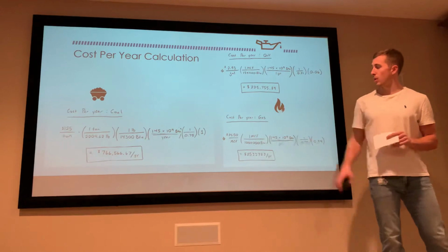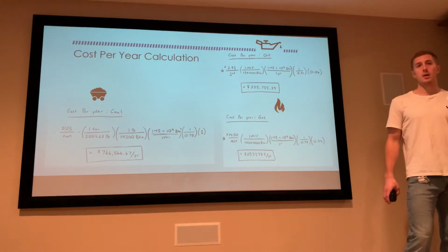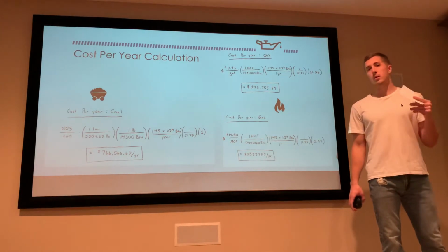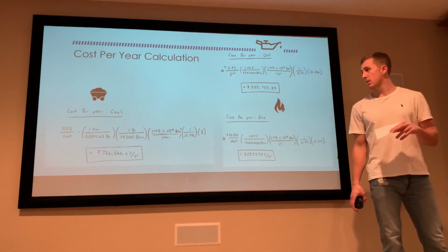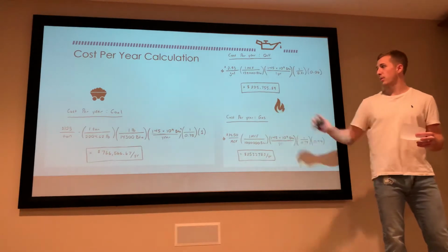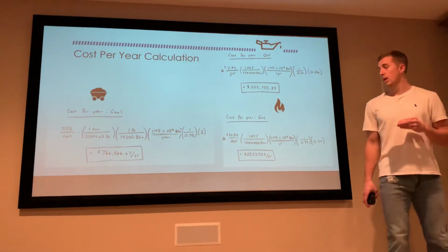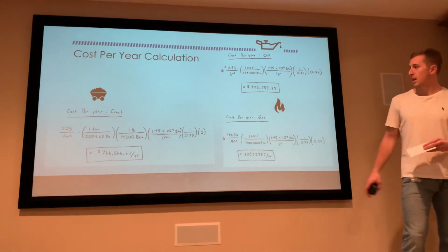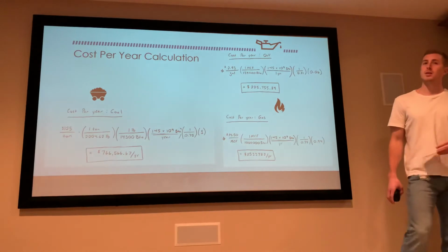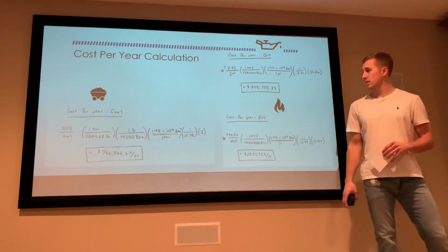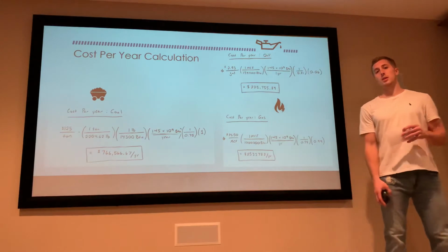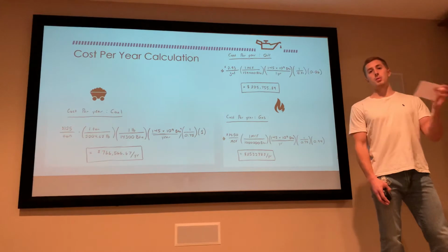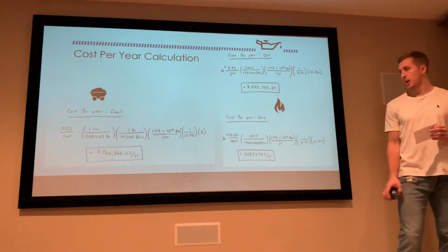We know that we must make 145 times 10 to the 9th BTUs of steam per year, so we multiply our equation by that. The 1 over 0.75 is the efficiency of this process, and then we multiply it by 1 because the coal operation does not require a switch-off, and it will be operating all the time, 100% of the time.